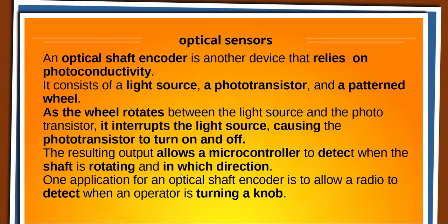Okay, optical sensors. You have shaft encoders, which you use in machine tools a lot to know the position. You also have what we call encoders, which most modern radios, if you have a knob, it's not turning a capacitor or a potentiometer, it's turning an encoder. In some cases, they're actually mechanical encoders where you're getting switches and you can feel them. Bourns also makes some that are contactless, where it's a smooth feeling like a real optical encoder, but it's actually making electrical connections.